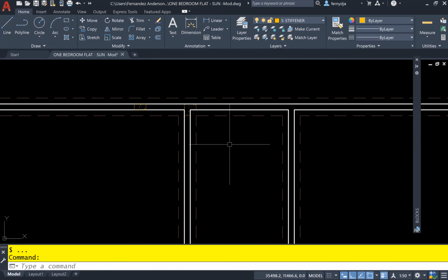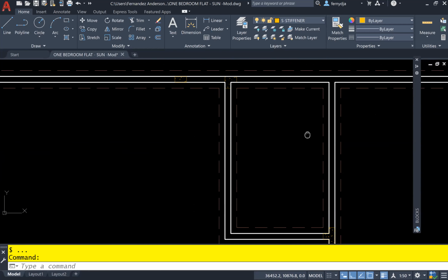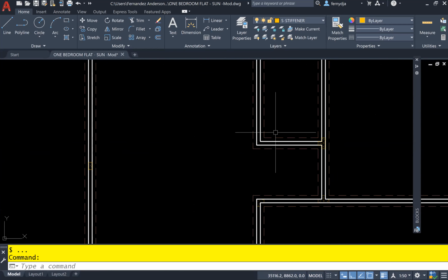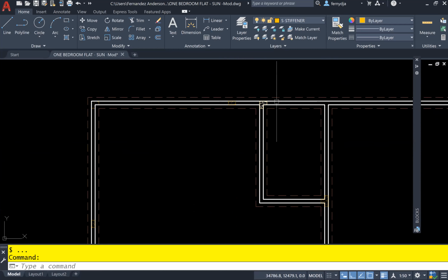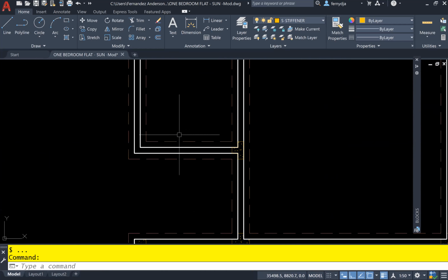Well, I didn't put a T-stiffener here because there's a door opening, but I didn't put a T-stiffener here and an L-stiffener here because this one is tying this wall and that wall, and the T-stiffener is tying that one. Certainly if I was going more than one floor, then I would need to put it at every intersection. But because it's a single story building, at the corners here, we just overlap the blocks and put the steel in and reinforce the corner. You don't have to put a stiffener at every single corner since we're not going up 2 stories.